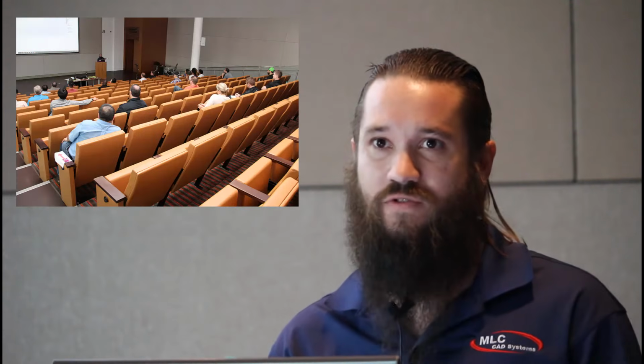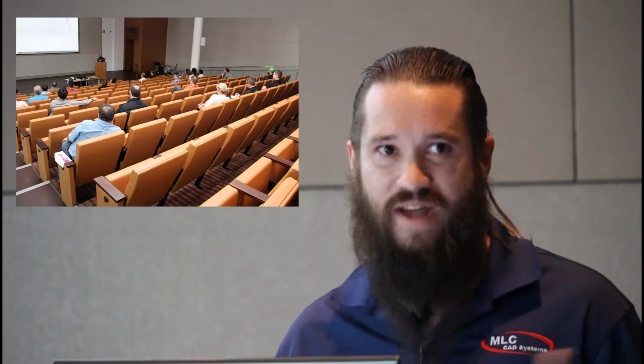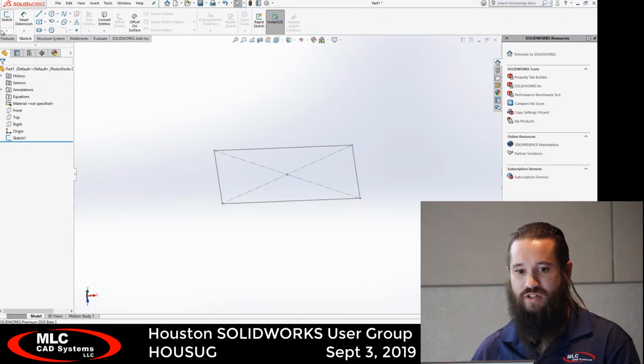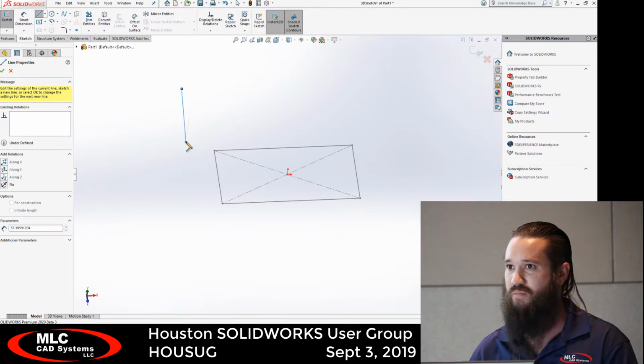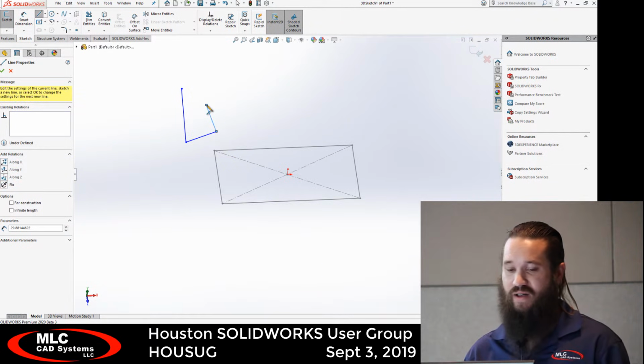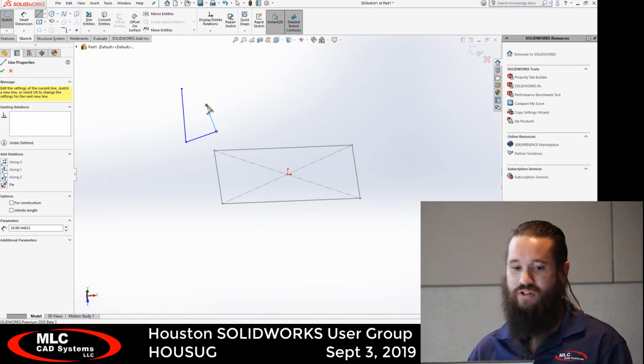A lot of times for weldments, because we're doing essentially a multi-body part, the weldment feature functionality does not merge the solids together. That's how we're able to get the individual detail items on our drawing for manufacturing. And because we get these things that come off at all obscure angles, it generally will require some type of 3D sketching. Now, those of you that have tried just 3D sketching from the start will probably say that it's pretty frustrating. Because we're not locked into a specific 3D sketch plane, which we can add, it gets really tedious to go through and start doing all these things.